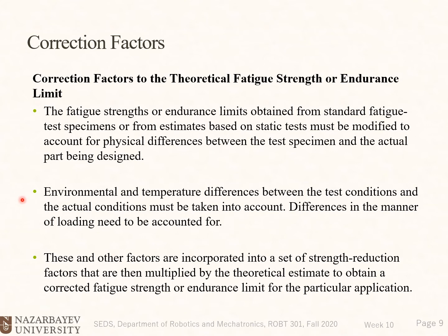Environmental and temperature differences between the test conditions and the actual conditions must be taken into account. Differences in the manner of loading need to be accounted for. These and other factors are incorporated into a set of strength reduction factors that are then multiplied by the theoretical estimates to obtain a corrected fatigue strength or endurance limit for the particular application.